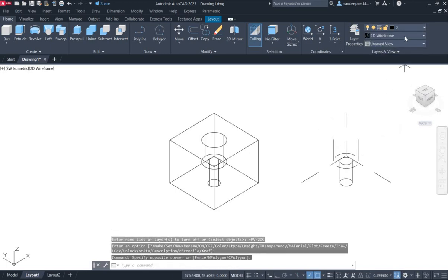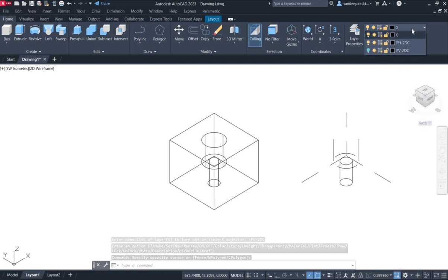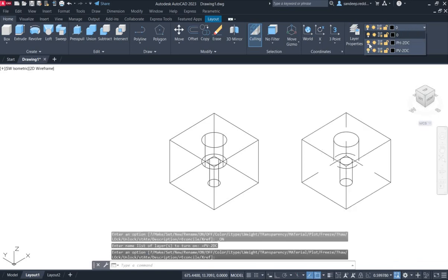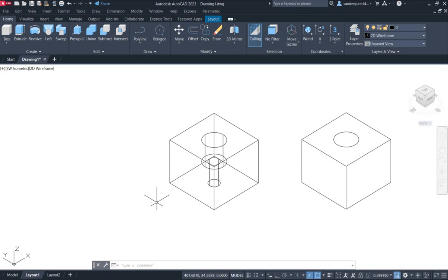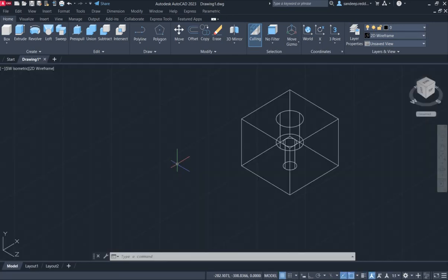As part of your Lab 5 exercise, you will be creating your 3D solid and then creating solid and hidden profiles using the solprof command, and then turning off the hidden profile while leaving the visible profile turned on in layers. So that's how the solprof command works. So far in this video we have covered section, slice, and hatch, and also just a while ago we understood how to create profiles of our drawings, solid and hidden profiles.